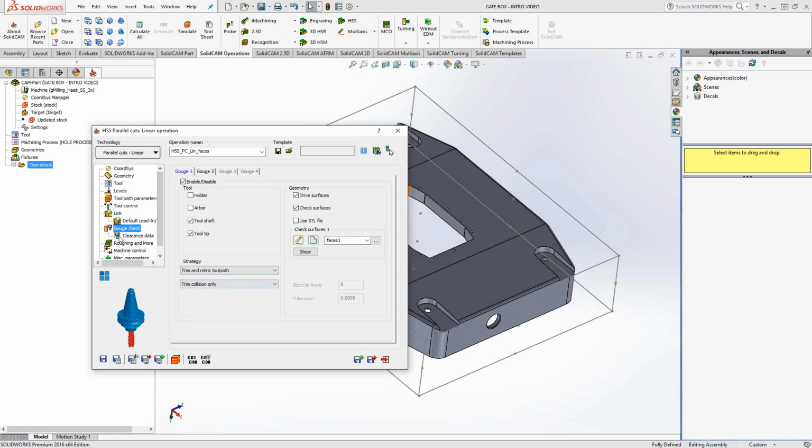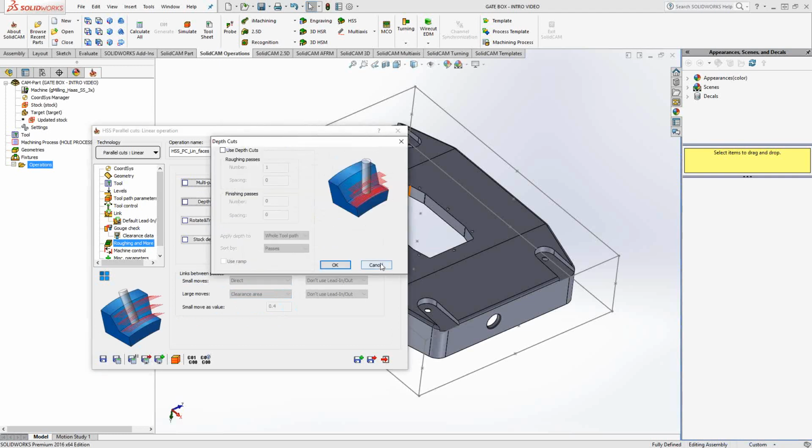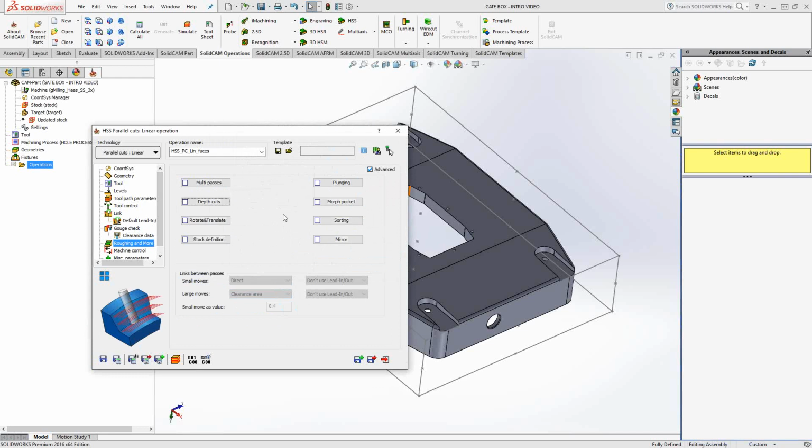Okay. And lastly, we have roughing and more. I mentioned before that this is a toolpath that is provided on all levels of our software, meaning that even on the basic one, if you need to do a 3D roughing toolpath, you have the ability to do that here by selecting the surface and then telling it how many radial steps and how many axial steps you'd like to take to machine that out.